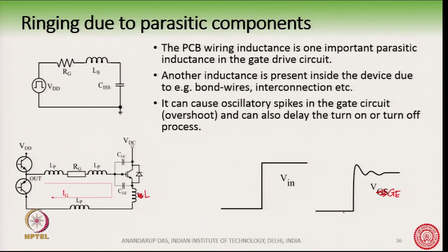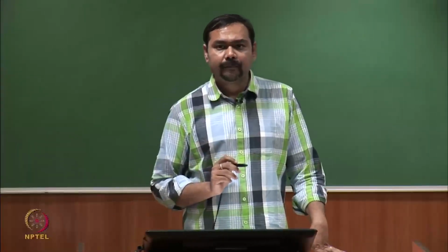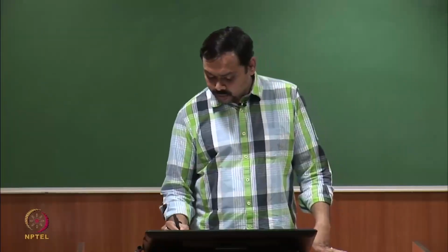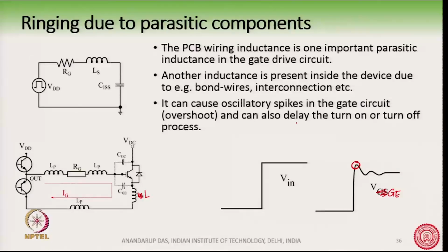This voltage will be oscillating in nature. This is because of the parasitic inductances in the circuit, but it must be kept in mind. So, what is the effect of this? Not only will there be a peak, but this can also delay the turn on process of the device. These are the important effects of this inductance.